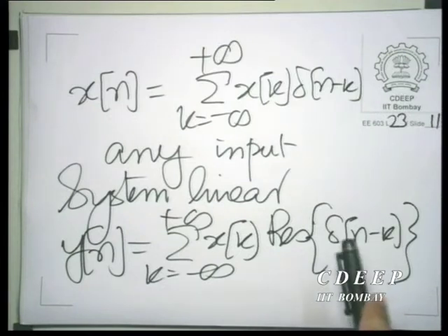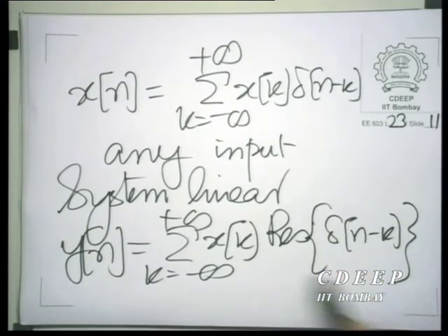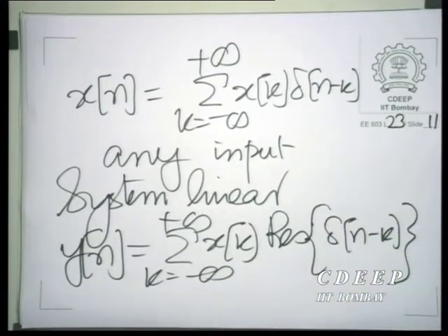And therefore, we can now write down y[n] in terms of all the responses to different impulses. That is true for any linear system. The only catch is that for a linear system which is not shift invariant, this cannot be written in terms of a single h[n]. Now, this question was meant to test one's understanding of the proof that LSI systems have an impulse response that characterizes them completely.